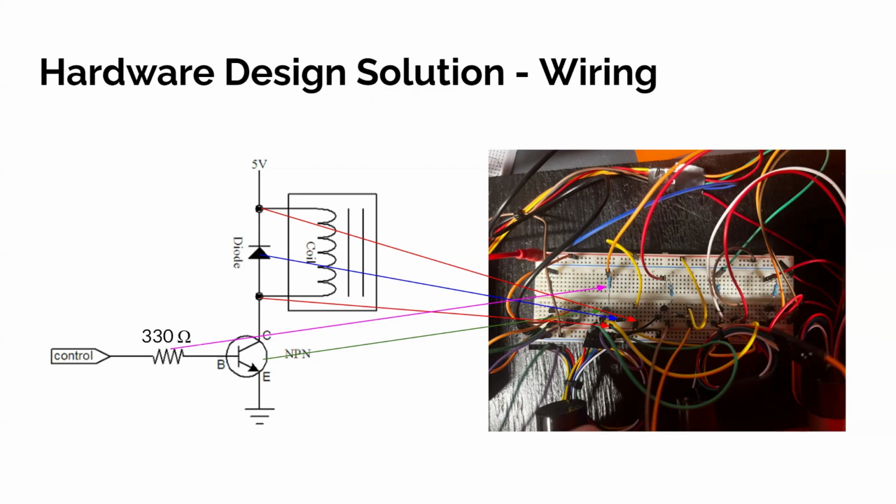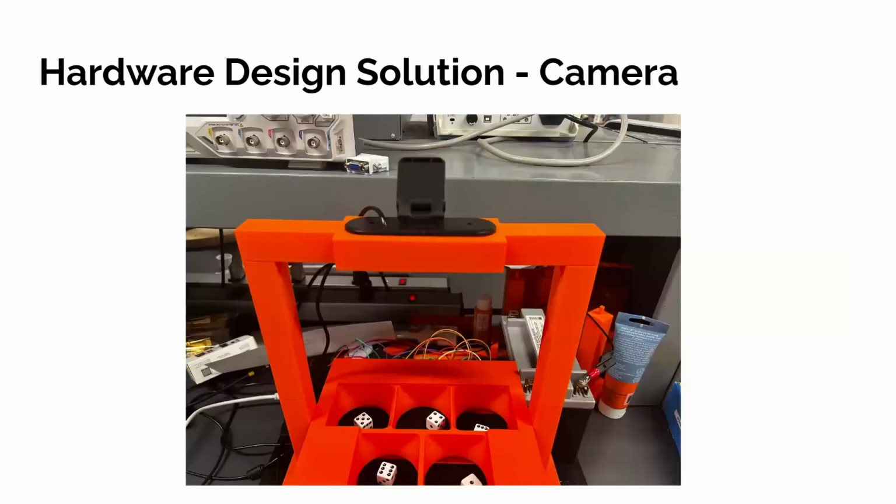The project required the circuit to be repeated for a total of 5 times, 1 to control each of the motors. The final part of the hardware design was the camera stand. Since the program software requires a fixed camera position for operation, it is essential to design a sturdy structure that will allow for consistent camera readings that would not move during gameplay. Our design involves 2 posts, 11 inches tall, with widened feet to ensure stability. A bar spans across both of the posts where the camera rests. The camera slides into an oval-shaped slot above the game board and is secured with no movement.